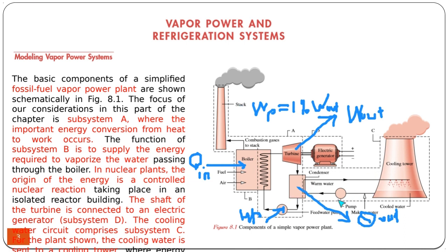As the water is heated inside the heat exchanger because it has condensed the vapor here, then it's heated a little, then this heated water is sprayed inside the cooling tower. As the water is sprayed into the cooling tower, it evaporates because of the air flowing around it. So there is a natural airflow inside the cooling tower, which evaporates some of the water sprayed here.